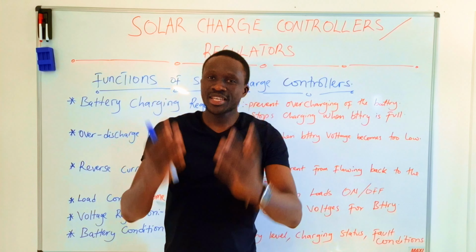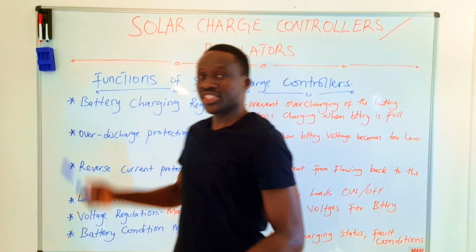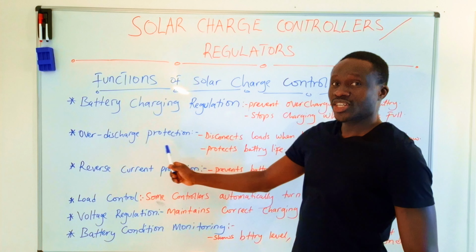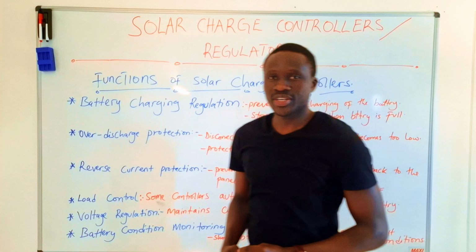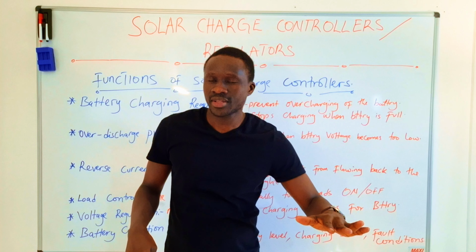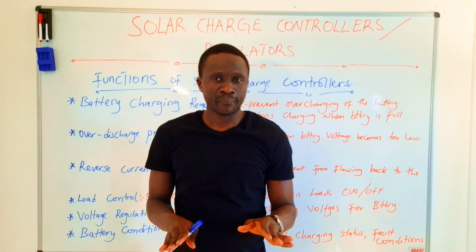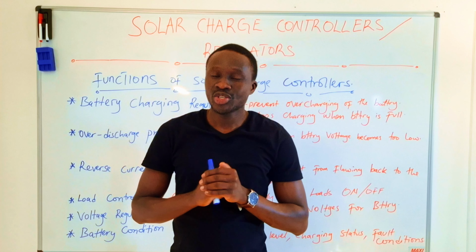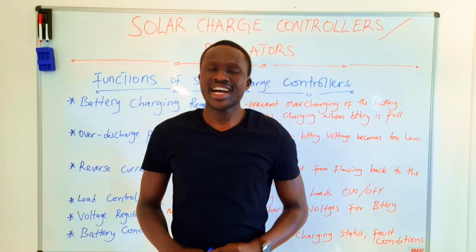And the client will say, wow, this technician did a very good job for me because of this charge controller, which is protecting your battery from over discharge. Okay? When the battery goes down to, let us say, 10 volts, it will disconnect all your loads. Its main purpose, it is automatic. Its main purpose is to protect the battery from over discharge. And we shall be happy.